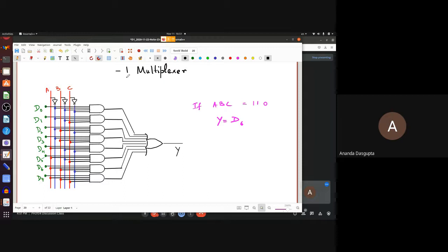8, simply because once again you are using 3 inputs, 8 possible input combinations, so you have an 8-to-1 multiplexer. If you wanted to build a 16-to-1 multiplexer, you would have to use 4 inputs. The pattern would be exactly the same. And here, note what we have done. This multiplexer is again a circuit. If you ignore this final thing here, which is an OR gate, the rest of the circuit is very similar to the demultiplexer, right?